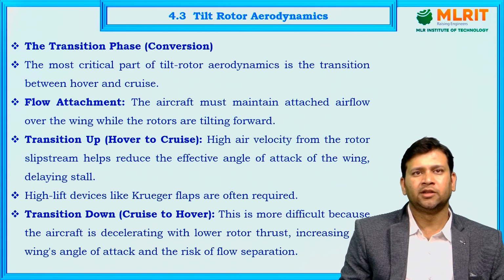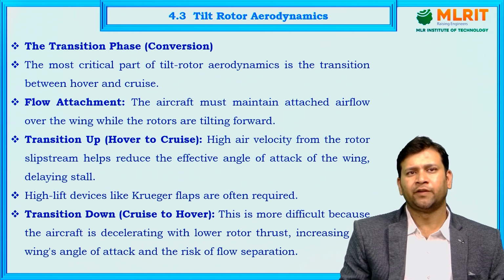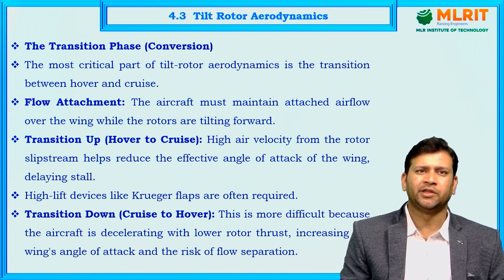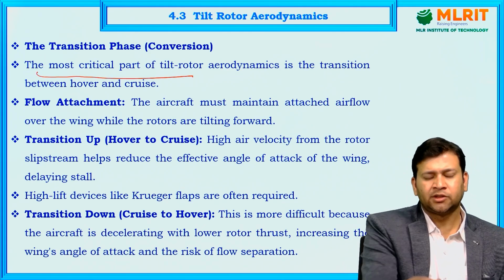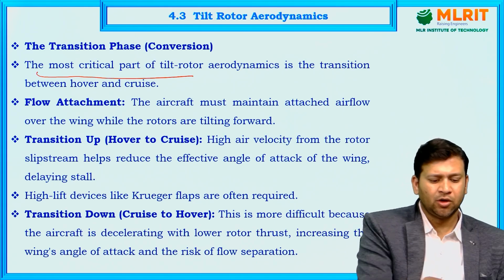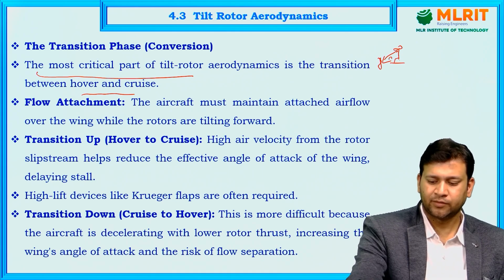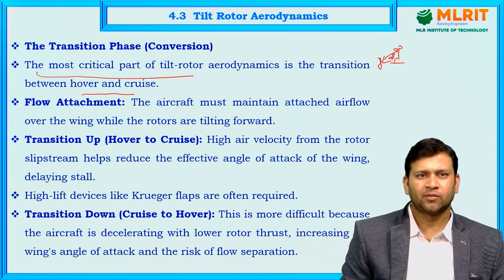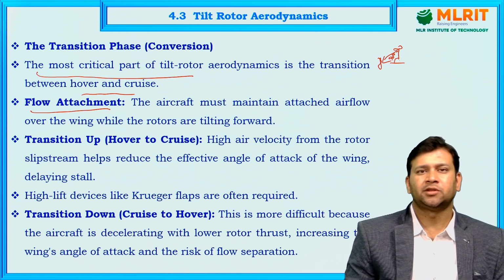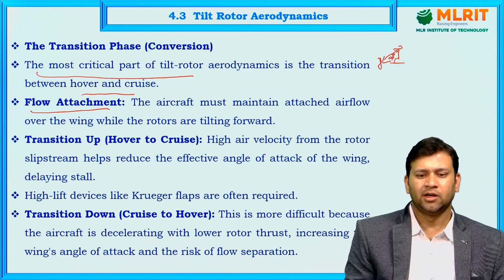Transition phase: the conversion from tilt rotor to propeller for forward flight is a very crucial phase in this kind of configuration, and it is quite challenging. The most critical part of tilt rotor aerodynamics is the transition between hover and cruise. When it is moving from this position to this position, when it is a rotor here and a propeller here, this is the most crucial phase in the tilt rotor flight. The first one is the flow attachment. The aircraft must maintain attached airflow over the wing while the rotors are tilting forward.